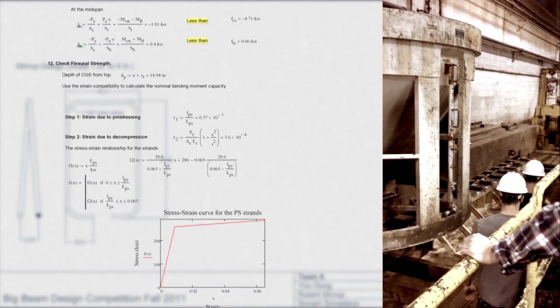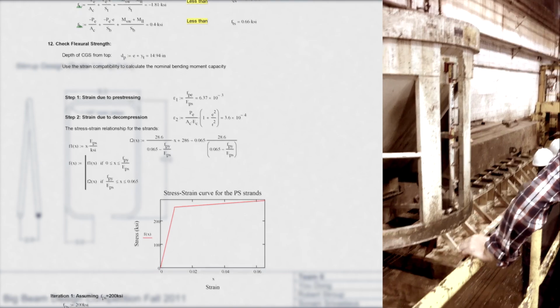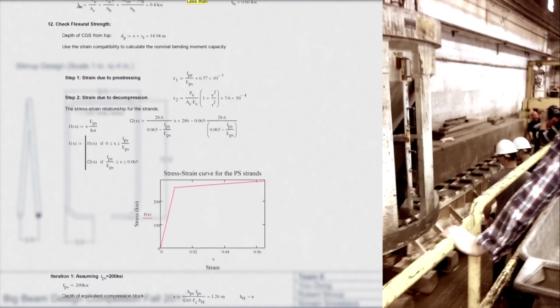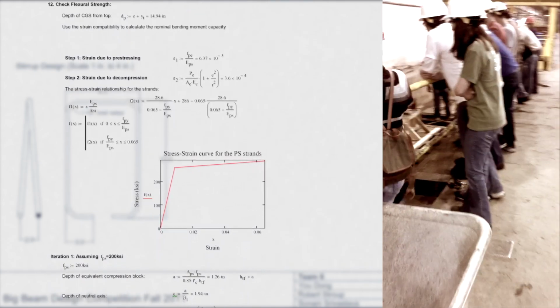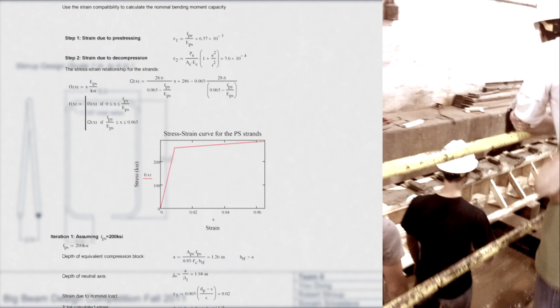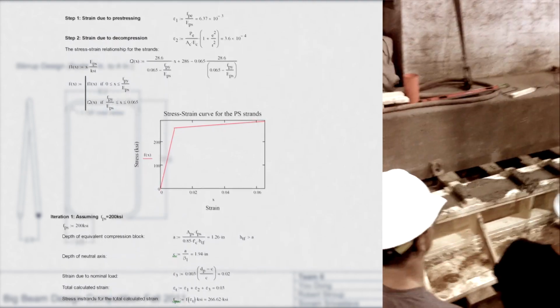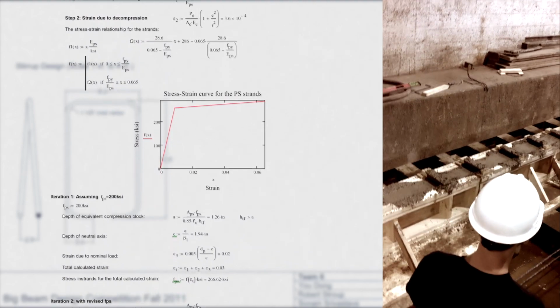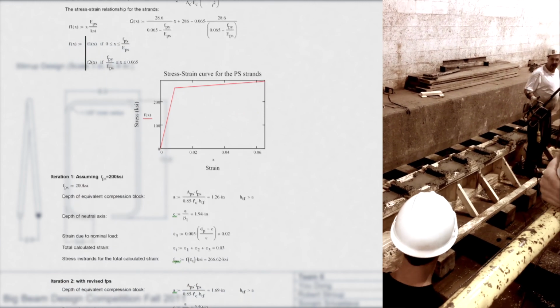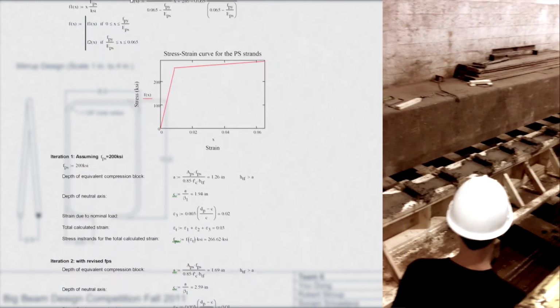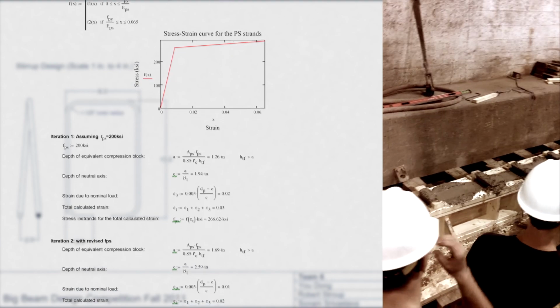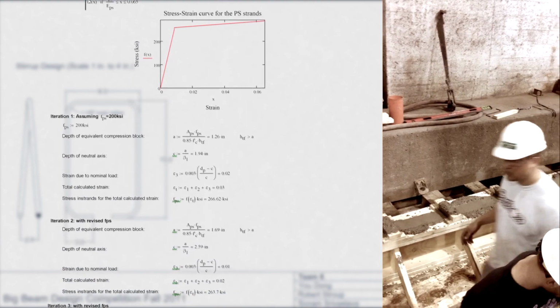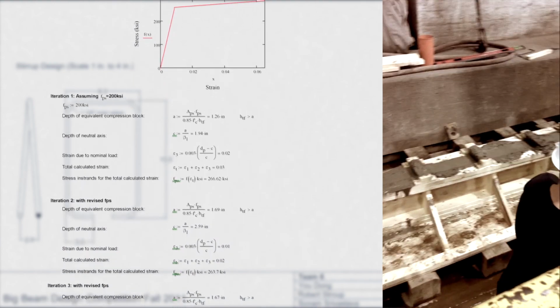Although this value was 3.84, which indicated that 4 bars would be required, we selected only 2 pre-tension bars and decided to compensate for the required remainder by designing additional longitudinal reinforcement in the compression zone. This gave us an early value of 0.34 square inches for pre-stressing steel in the tensile portion of the big beam. Our pre-stressing losses were as follows.